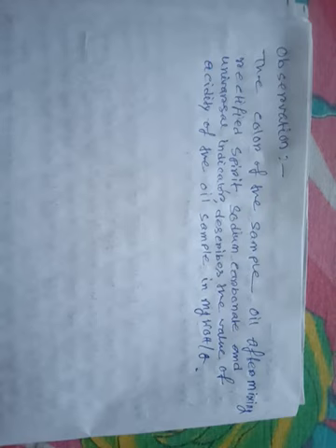After making a solution of sodium carbonate, mineral oil and 5 drops of indicator, we observe the color of the sample. After mixing the rectified spirit, the sodium carbonate and the universal indicator, the color describes the value of the acidity of the oil sample in milligrams KOH per gram. KOH, the potassium hydroxide. It is the procedure of acidity test of mineral oil.